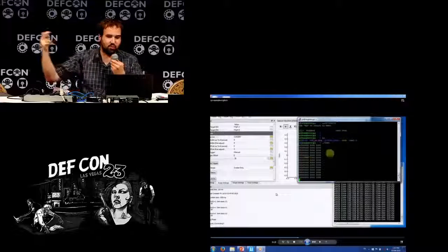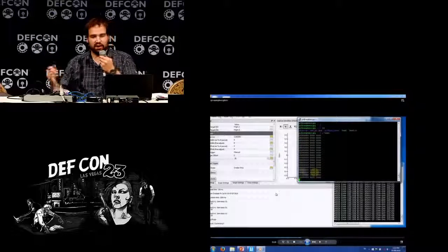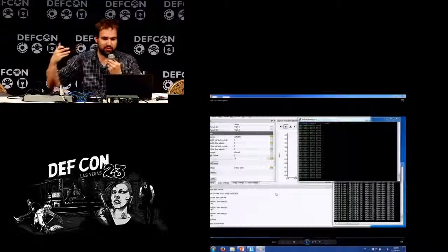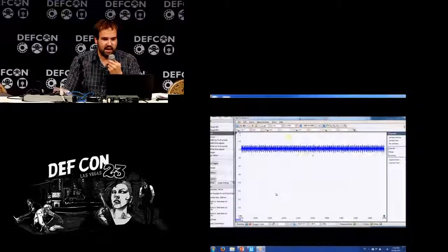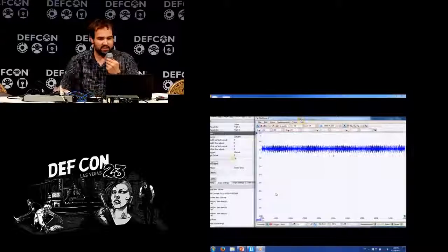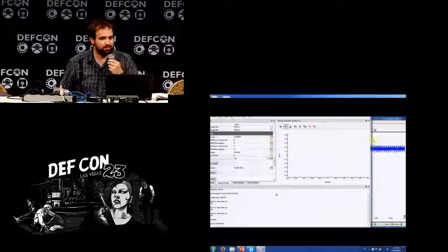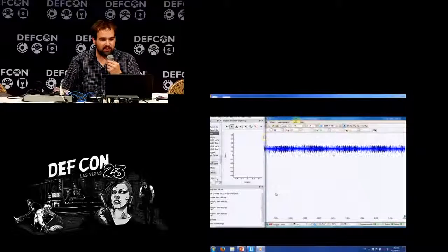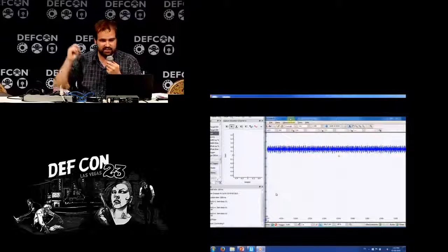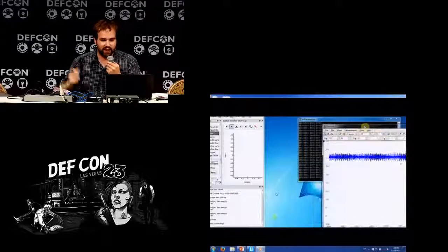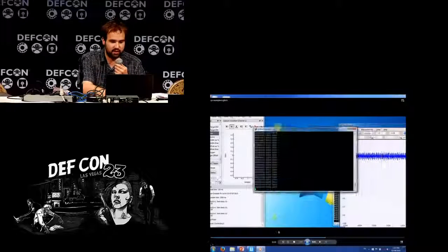And you can see the correct output is 25 million, 5,000, 5,000. So it ran through both loops 5,000 times, incrementing the final value 25 million times. This is the 1.2 volt rail, the core voltage for the Raspberry Pi. And when we hit a trigger button, it's just generating a glitch. If you want to generate a glitch, you could make an Arduino code to do this. You can use a signal generator, anything that can activate that MOSFET for the correct period of time.